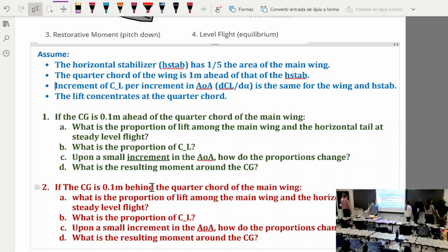So this provides negative lift, which means the horizontal stabilizer is going to be at negative angle of attack, right? So if you pitch up, the negative is going to become less negative. Another way to think about it is if you make it point up, then the lift is going to be negative 1.6 of this. Essentially, as you pitch up, anything that provides negative lift is going to be less negative and eventually become positive. So when you are looking at a delta, the deltas actually have different signs. So it's going to increase by.